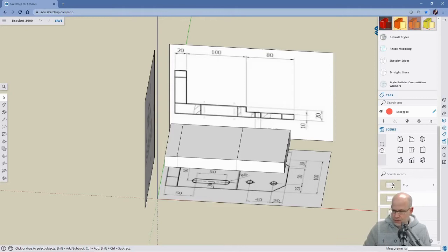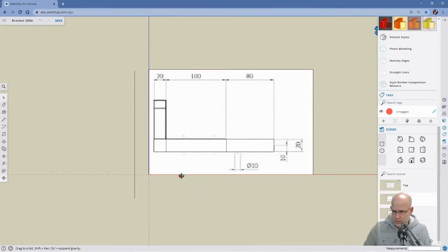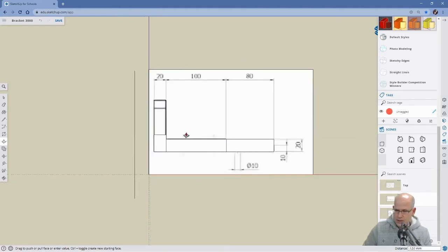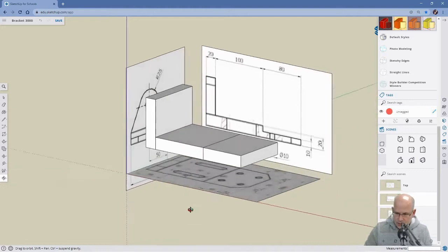All right. So let's see. We want to go back to side view. I want to bring up push-pull. Actually, I don't need to extend. I don't really need to extend this face, so I can just do without the control button right now. Bring this up. I'm going to click side here. And I'm going to bring it up to right there. Okay. All right. Starting to come together.